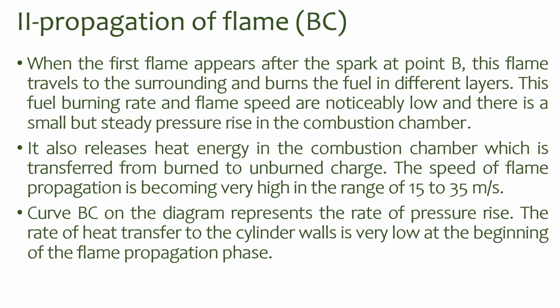It also releases heat energy in the combustion chamber, which is transferred from the burnt to the unburned charge. The speed of flame propagation becomes very high, in the range of 15 to 35 meters per second. The curve BC on this diagram represents the rate of pressure rise. The rate of heat transfer to the cylinder walls is very low at the beginning of this flame propagation phase.